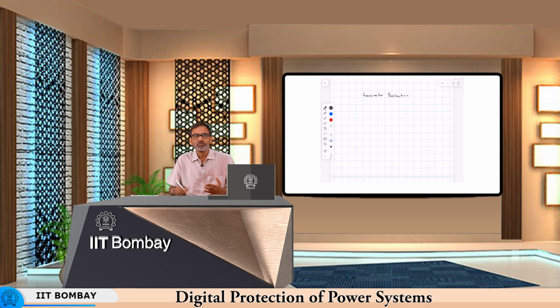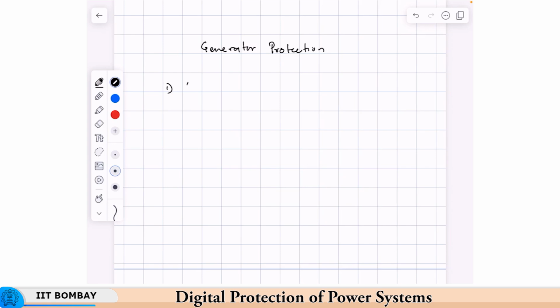Now, there could be, as I said, a few nuances. Other than the faults itself, there could be some conditions known as adverse system interaction. Because we are talking specifically of synchronous generators, they could lose synchronism, that is go out of step, and these can cause large variations in voltages and currents, which could even damage the generator permanently. So, they also have to be protected against.